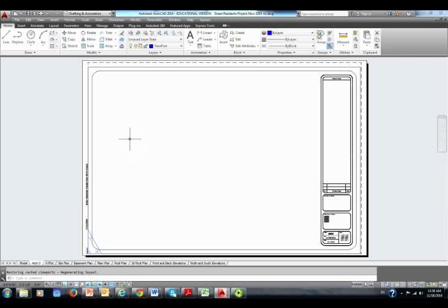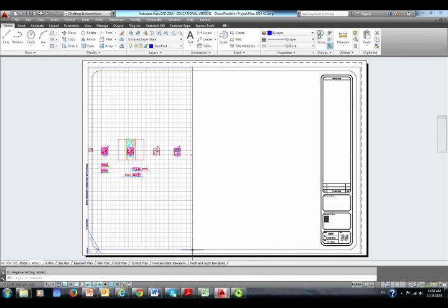So let's make a couple viewports. MView. So let's say on this drawing I want to create, and you see this is my dilemma here. So I'll go from here to nearest here, near, and pick a viewport that will kind of have proportions of site plan. So let's say I'll do site plan that on most of your projects shows floor plan, and then a couple elevations on the side. Okay, so I'm going to do this.